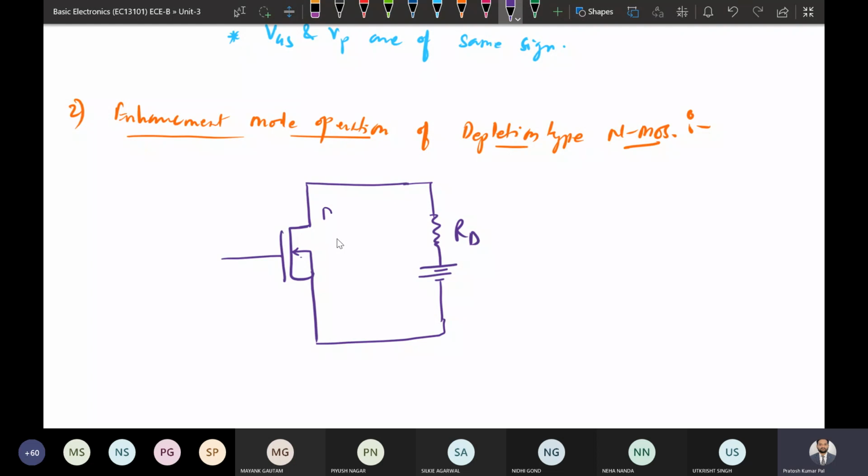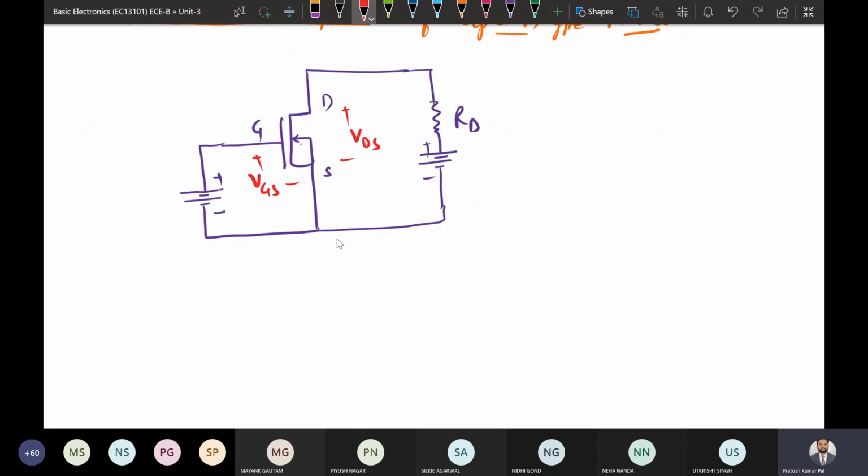So this is source. The drain and source should be positively biased, and the gate terminal is now going to be biased in the positive direction also. So the gate is this one, so gate to source will also be biased such that, okay, this is VDS and this is VGS. So already it is having a channel, and also we are going to bias it such that the gate to source voltage is having the positive bias. Again here the current direction will be like this.